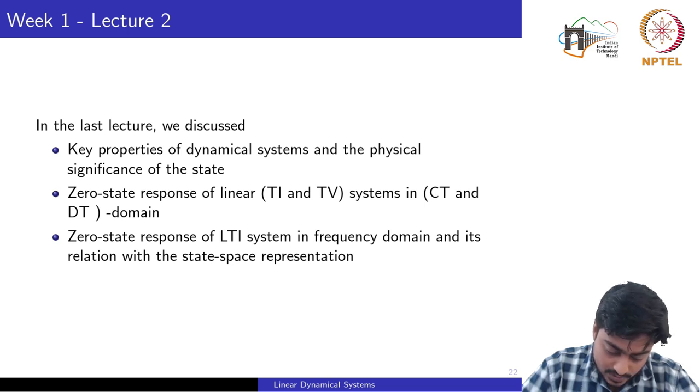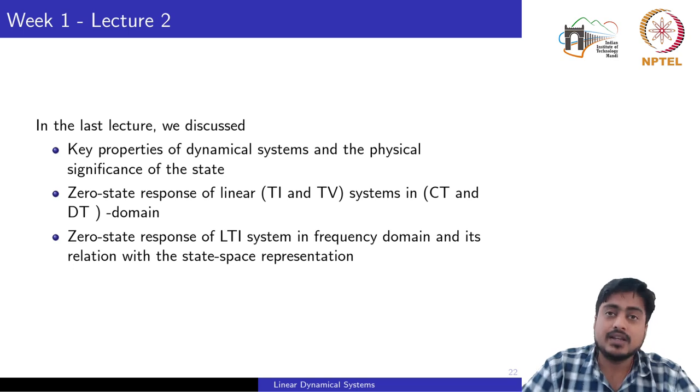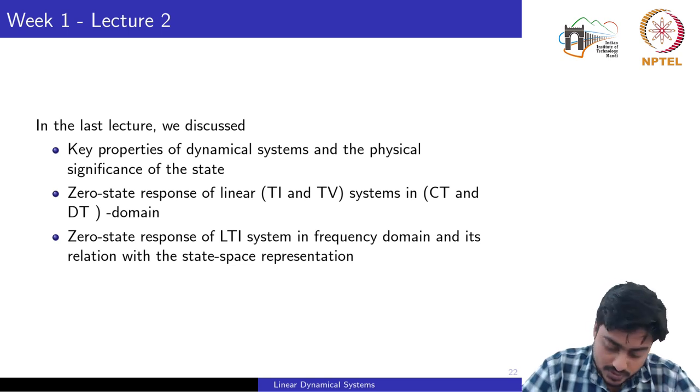Third, particularly for the LTI system, we discussed its solution in the frequency domain, because we saw that if we want to compute the response in the time domain, you need to compute the integral and the convolution. So we used the Laplace transform as a tool to compute the response in the frequency domain first, and then by taking the inverse Laplace, we computed its solution in the time domain. We also saw the relation of the zero state response with the state space representation of the system.